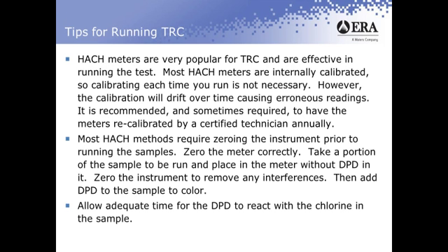What happens is, over time, those DPD pillows tend to weather, as chemicals will. Weathering means that the chemical isn't as strong or as potent as it was when it was fresh. So as those chemicals weather, it might take more than 2 or 3 minutes for your reaction to come to completion.